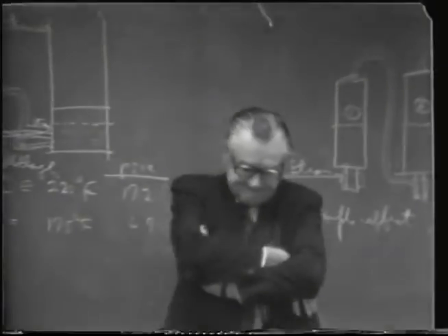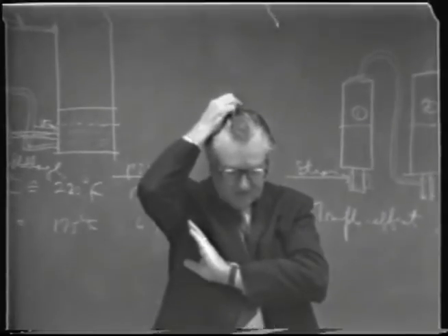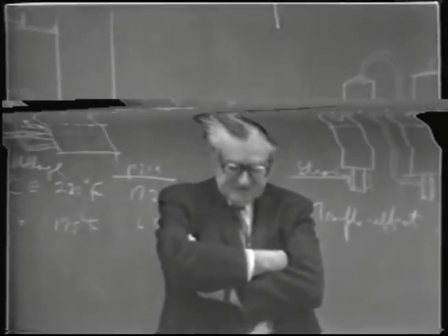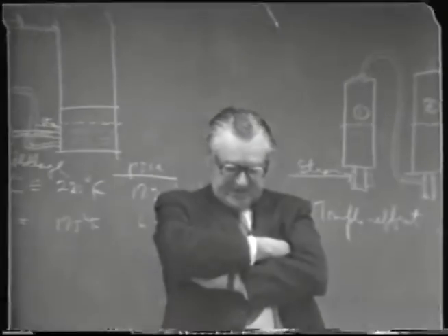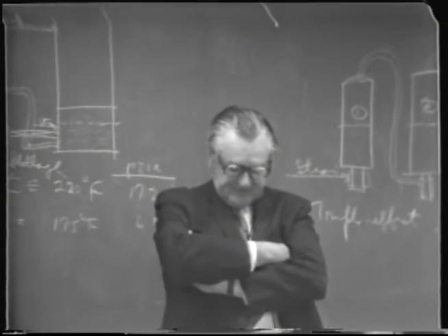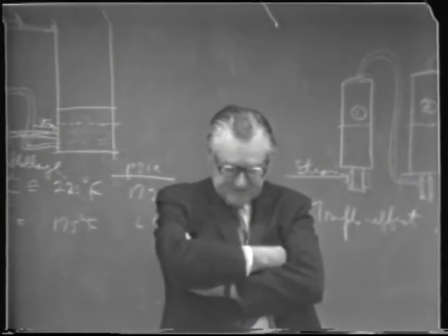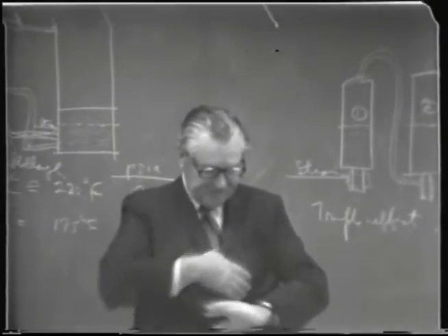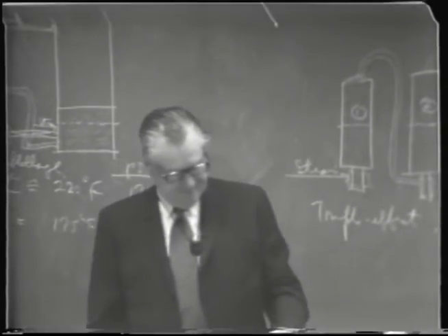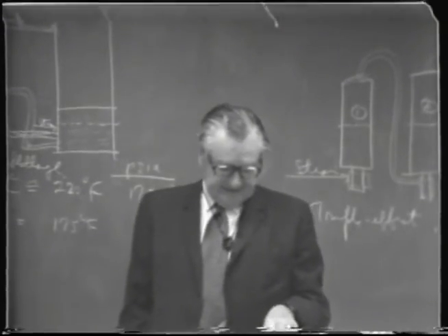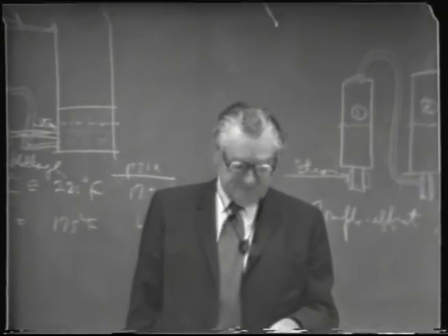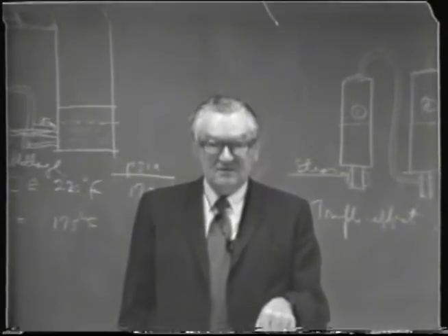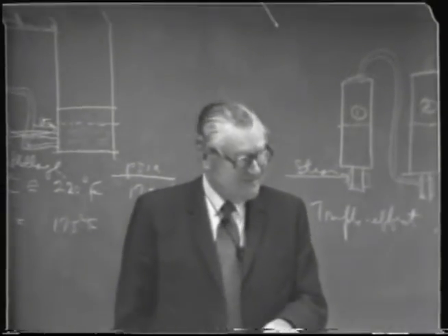But anyway, pattern D illustrates the combination of a primary concentrating and a stripping and concentrating column arranged as a split column, in which the main product is drawn off from the concentrating section as a side stream, and an appreciable heads cut is taken from the top of the condenser and then fed into a separate heads concentrating column, which has its own stripping section and concentrating section.